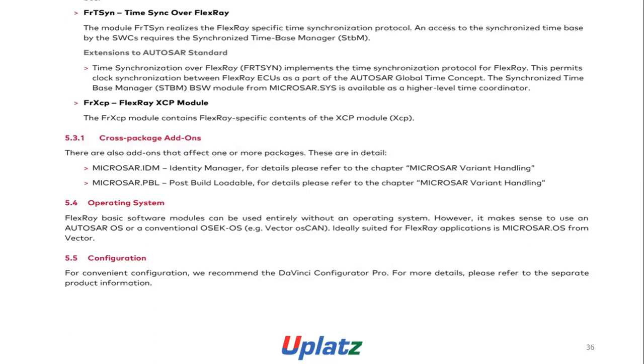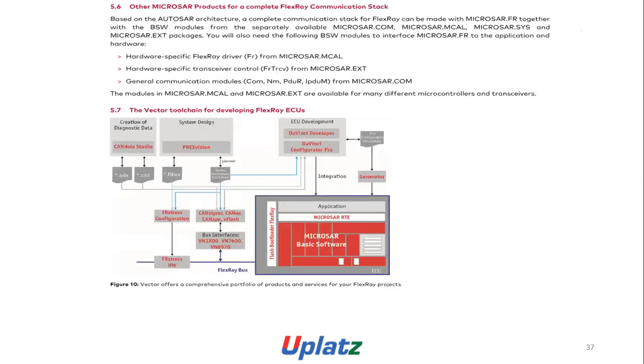However, it makes sense to use an AUTOSAR OS or a conventional OS, for example, OSEK-OS. The OS can be MICROSAR.OS from Vector. Configuration: for convenient configuration, we recommend the DaVinci Configurator Pro. For details, please refer to the separate product information.